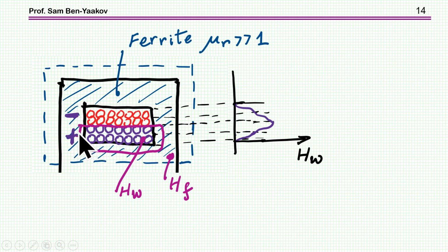Now, if I choose another path, which goes up to two layers, the magnetic field will be higher because I'm now encircling much higher ampere turns, twice in this case. So typically what I'm going to see is that at the beginning, the magnetic field is 0. Then as I'm passing through the first layer, it's going up. The second layer is going even higher. And then since the secondary current is in the opposite direction, in a transformer the primary and secondary currents in fact cancel each other. Then as I encircle the third row, the magnetic field H will go down, and then it'll go down farther. So this will be a profile of the magnetic field within this window.